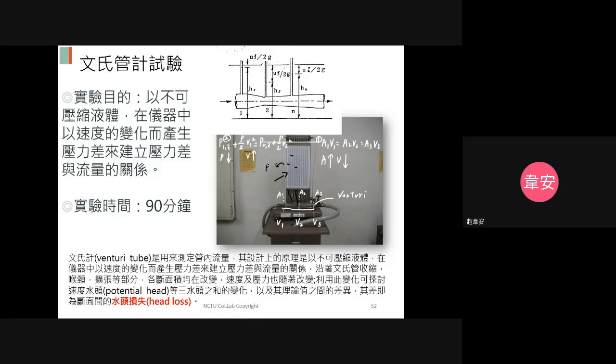So this pressure is directly from the pipe. So we know the true pressures, but based on the continuity equation and the Bernoulli equation, we can predict theoretical pressures. So we just compare the theoretical values and the observed values. There will be some difference.